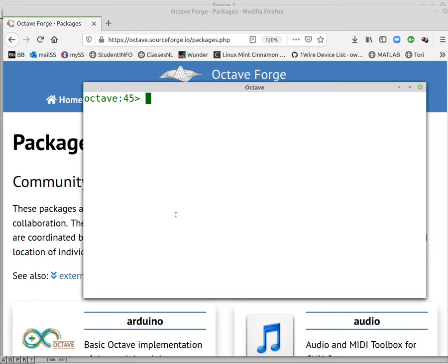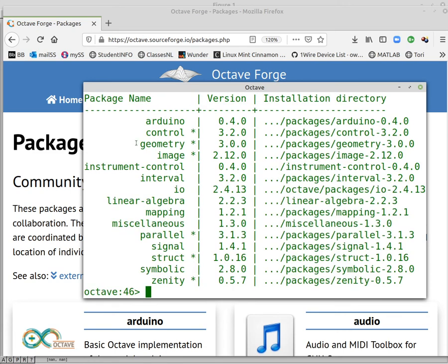Alright, so I just showed you how to do the simulation using standard Euler simulation of the transfer function 1 over s plus 5. Alright, but now what I want to do is show you another method. Both Octave and MATLAB have what they call a controls package. If you run package list in Octave, it'll list the packages you have installed, and you have to have the control package installed and loaded.